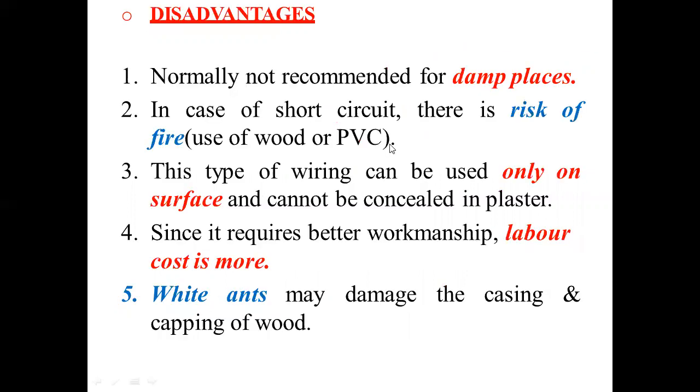But the disadvantage is that it is normally not recommended for damp places. In case of short circuit, there is a risk of fire because of using the wood or PVC material, and it requires better workmanship, which means the labor cost is also very high, and white ants may damage the casing and capping of wood. So that is another disadvantage of using this type of wiring.